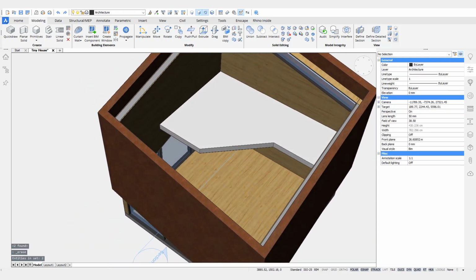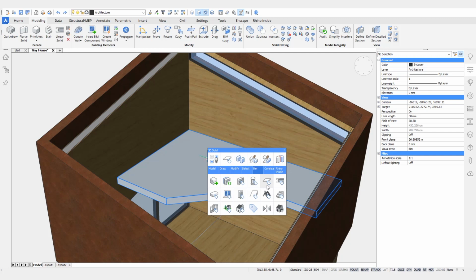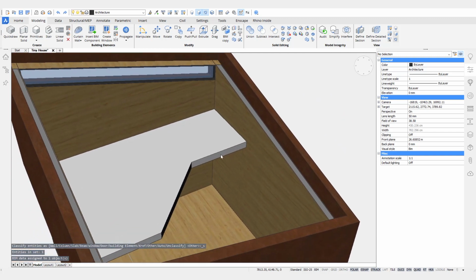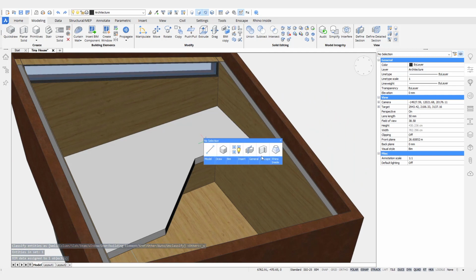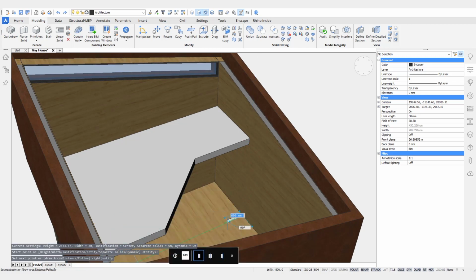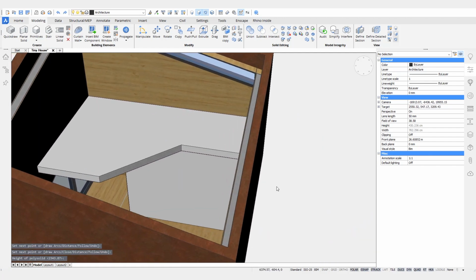Currently, again, it's just a solid. I can classify it if I want to, but it's not necessary yet. I'll just do it. And also, I want to create a bathroom because every building needs a bathroom, of course. I'm going to do that using the polysolid tool. So this is a tool to easily create walls, but actually they're not walls yet. They're still just simple solids, which then can later be classified manually or automatically by, for instance, Bimify.